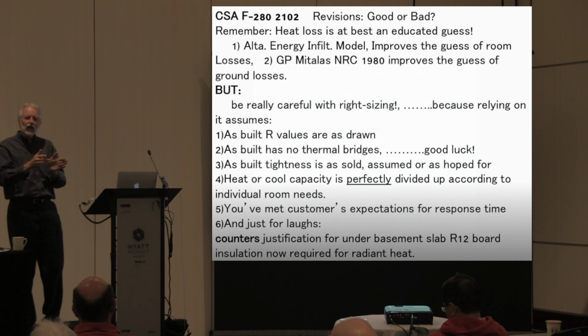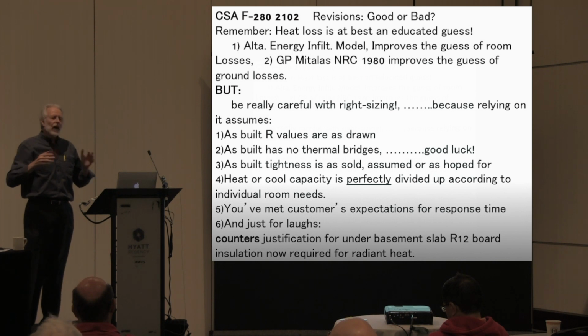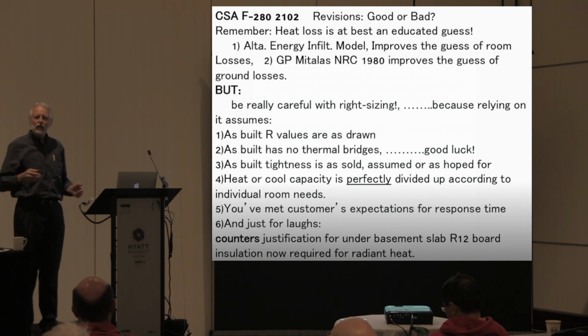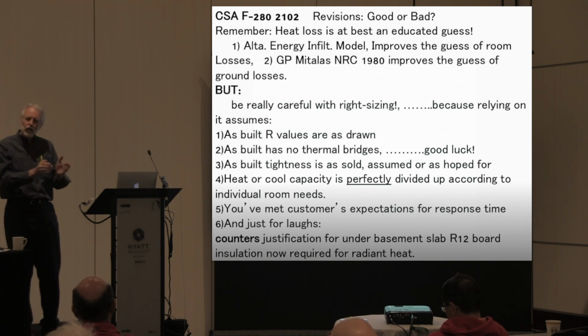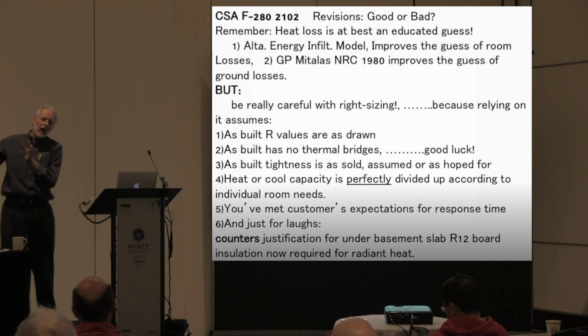Insulation at R20, R30 is good. But you thermal break with a lousy half inch or five-eighths of an inch of Dow board, like Scott was saying, in the slab edge. Your surface areas are small. The R value doesn't matter. You're thermally breaking it. So in your mind, remember, you differentiate between thermal bridge protection and R values. They're different animals.